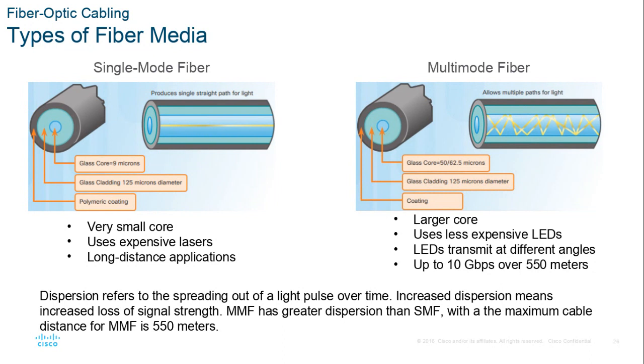So the rule of thumb used to be that we would run single mode fiber, maybe the phone company or the internet service provider would run single mode fiber miles and miles and miles between facilities. And we use multi-mode fiber within a commercial office building environment. These days, though, throw out the multi-mode fiber. Just use single mode fiber for everything.